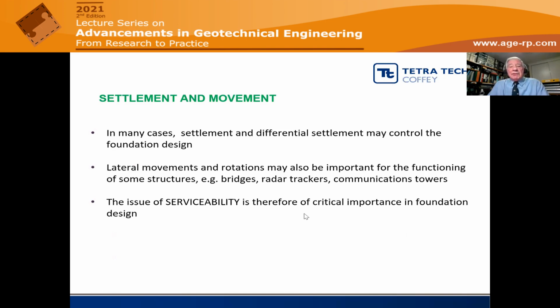In terms of the settlement and movement assessment, that may well control the foundation design. Certainly in many tall building cases, it's not so much the ultimate capacity, but the settlement and differential settlement that is the controlling factor. There may also be certain structures where lateral movements are important, for example bridge foundations, radar trackers or communication towers, where you need a high degree of stability of the structure.